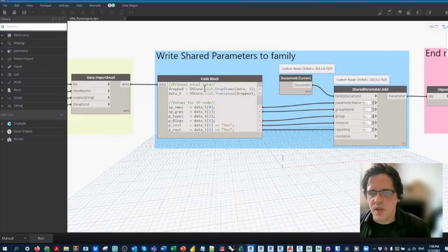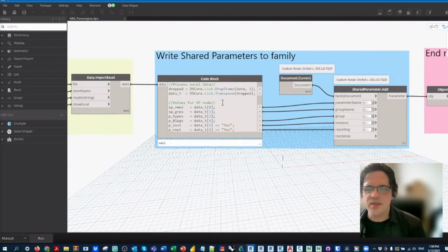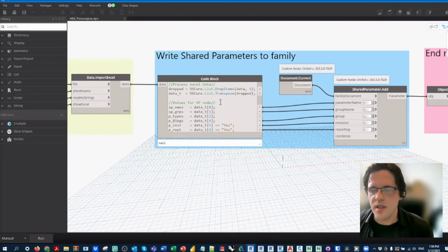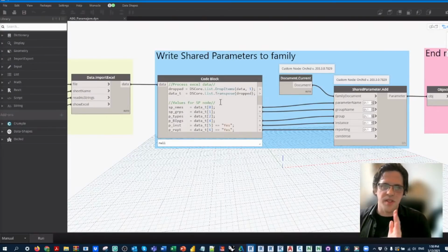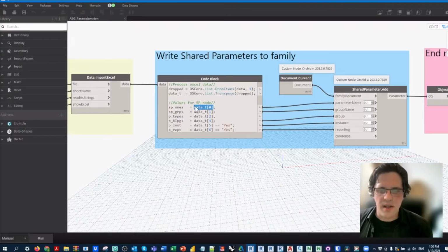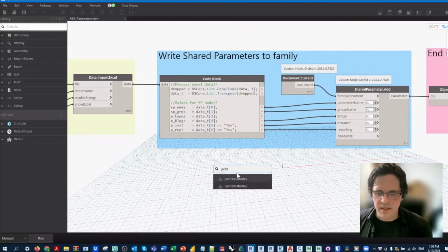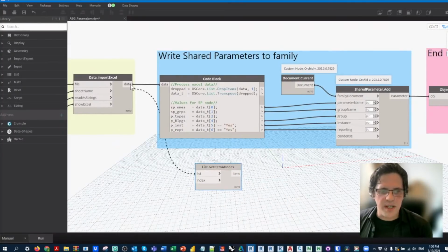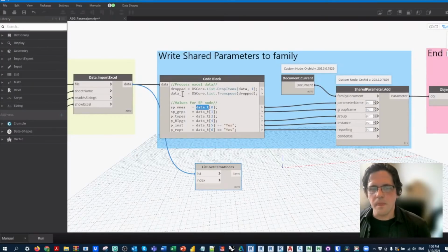What I'm doing here is using what's called DesignScript, which is sort of like a second step in Dynamo. Once you're more comfortable with nodes, you start transitioning to a written language in Dynamo. I find this is the middle ground between Dynamo and Python. You start using syntax that might look a little more complicated, but is really doing the same thing as visual nodes. This thing here is effectively the same as taking the first item from a list. But in this case, I'm just turning this into a variable.